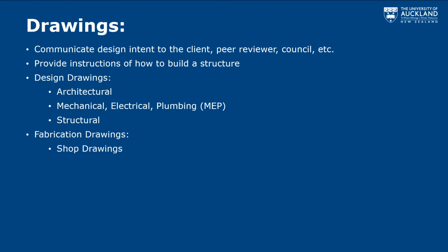So sometimes shop drawings will be used for an offsite facility, a fabrication workshop or a precast factory, to build the components, which will then come up on site, and then the structural design drawings will show how those components go together. As a structural engineer, you will need to review shop drawings as well, to make sure that the outfit doing the fabrication has interpreted your design drawings correctly and that everything will fit together. So that's the type of drawings that we have.